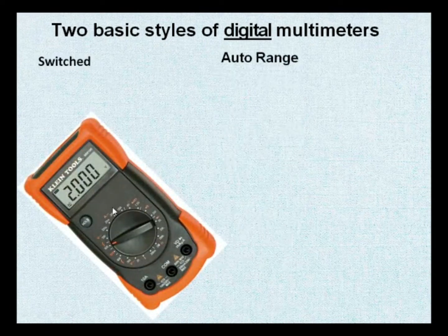However, here is the dial and the pointer of the dial. And over here on the switched, you have to set the type of the measured quantity that you're going to measure, like, let's say, for example, voltage. And you're also going to be able to set the range. So let's say you're going to measure voltage from a power supply that is going to be something around 30 volts. So you're going to set the range of up to 30 volts. And if you can't find an up to 30 volts range on the voltmeter settings, then you're going to go to the next up.